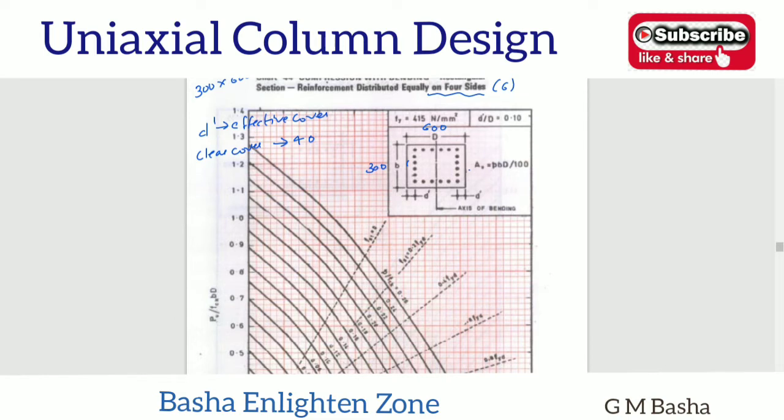Then I am choosing a bar diameter of 25. If I choose some 20 bar and take the center of that bar as 50, then after trials we will get some extra bar. For example, if I choose a 20 dia bar and by placing I get 25, your clear cover will be lesser than what you assumed. Therefore, I am taking 25 as the minimum clear cover in my condition for safety purpose.